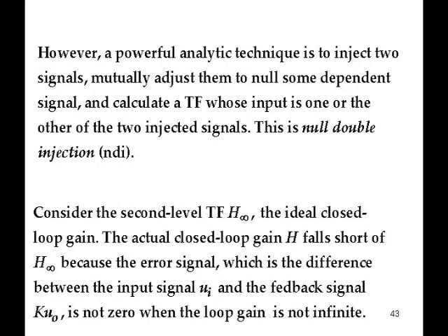A powerful analysis technique is to inject 2 signals, mutually adjust them to null some dependent signal, and calculate a transfer function whose input is one or the other of those 2 injected signals. That's called null double injection, NDI. And if you've heard anything about the extra element theorem, you remember that null double injection is the basic technique used to calculate one of those 2 driving point impedances, the Zn.